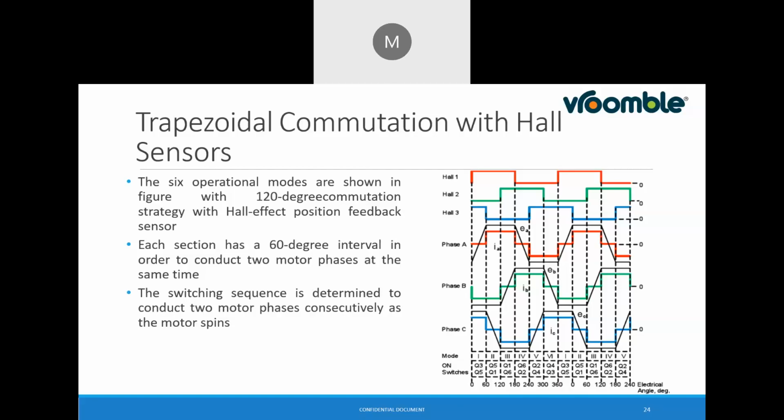So eventually, the Hall sensors 1, 2, and 3 will continuously give the position of the pole pairs, you can say, or the phase position, and one by one the phases will be powered up, and there will be a rotation of the motor through the switching, right?